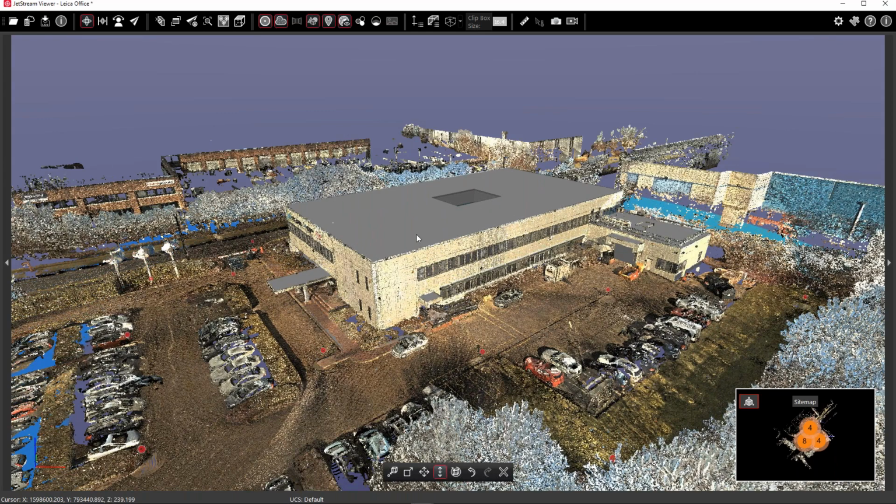Which export format works best in CAD and which works best in Revit? Great question. To be honest, if we're going to export in an LGS format, if we have Publisher or Publisher Pro, it's my opinion that the LGS is the better format because we can use that with Leica's CloudWorks product. And CloudWorks Ultimate would provide us a license for AutoCAD and Revit. So we could open the point cloud in either software.